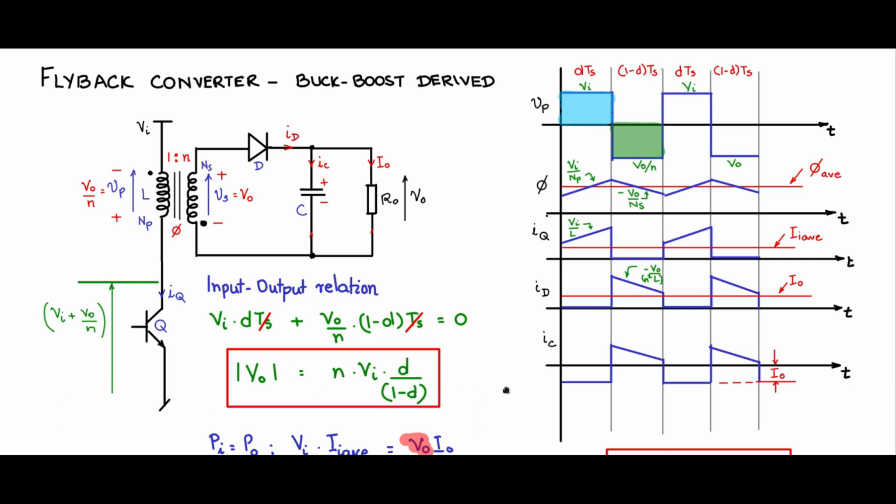So in this fashion we have this flyback converter, this is the functional schematic of that, and it's very, very popular. You can also have multiple outputs. You can have multiple secondary windings wound across the inductor, and you can take out isolated multiple outputs from this flyback type converter.